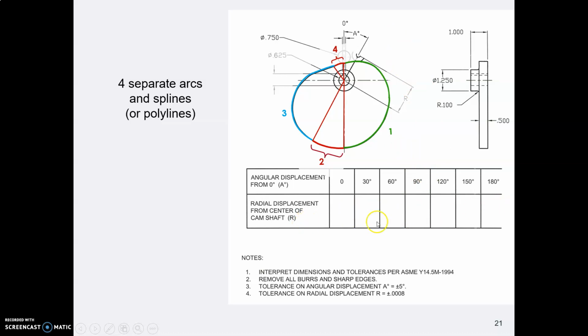You'll have numbers in here, of course, and the keyway will need depth tolerance and width tolerance. Notice you also have a diameter for the size of the hole in there, and a diameter for the size of the hub, a radius where the hub joins the plate, the thickness of the plate, and the thickness of the hub. Oh, and the size of the follower, which is 3/4 of an inch in diameter. Whew! So now we'll go look at how to do this in your particular drawing.